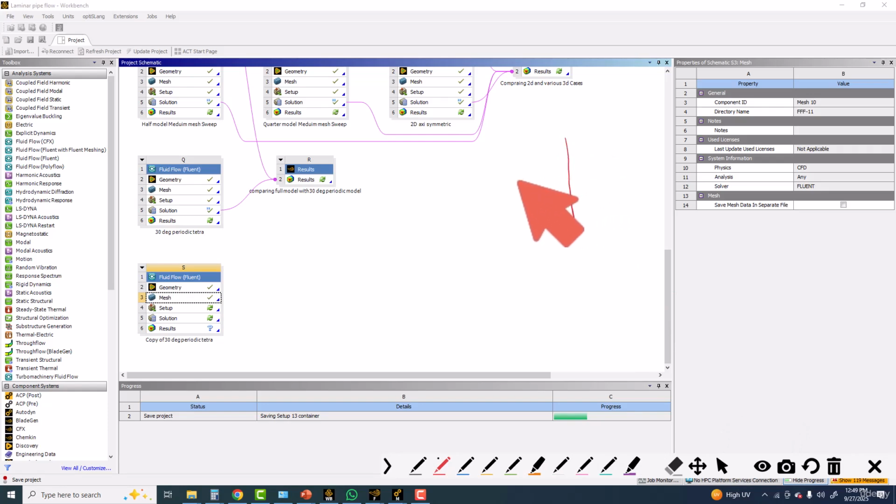So for example, if I have this circular cylinder, I can use these walls, these boundaries, as a symmetry. If I reflect, this part will be exactly a copy of this part. So this will be reflected here, and this part will be made. And when I have the symmetry on the bottom side, this will reflect this whole thing, and I will get the complete circular cylinder. This front part of your cylinder, and definitely in 3D you will get a complete cylinder. So this is the thing here.